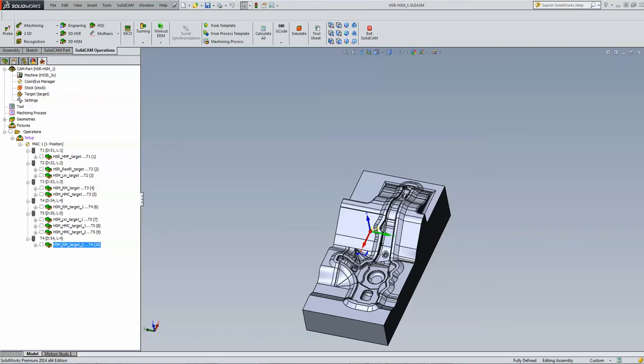Okay, let me just look at some of the questions we have here. One question was, does Quick Solid Verify work when you are machining prismatic parts? Yes, if the operation is a 3D operation, it'll work in any case. But when you're using 2D operations, it'll be too jumpy on the part itself. However, using it on prismatic parts, if you're using 3D machining, it'll work there really, really well.